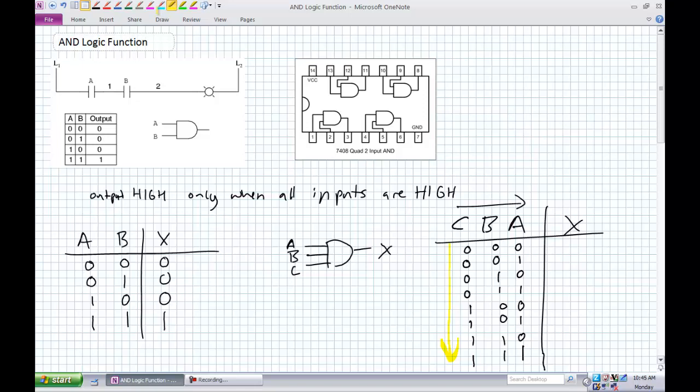and you don't know how your truth table works because you're skipping that one particular section. Additionally, notice, and we're going to go into Boolean numbers, binary numbers in a little bit here. How many possible combinations of one input can I have? Well, from our NOT gate, we have 2. Here's number of ins, number of combos. Now I have 2 inputs, I've got 4 possible combinations of inputs.